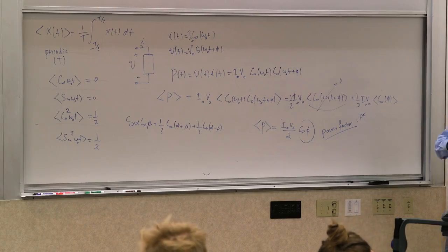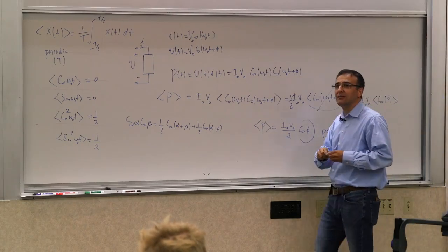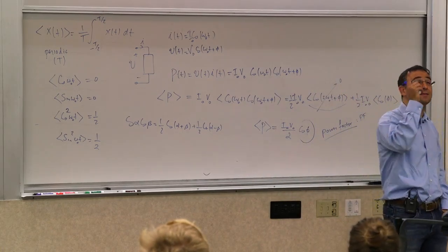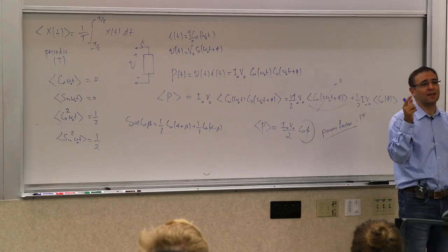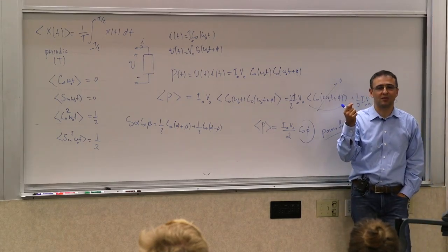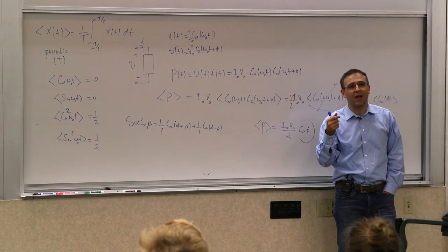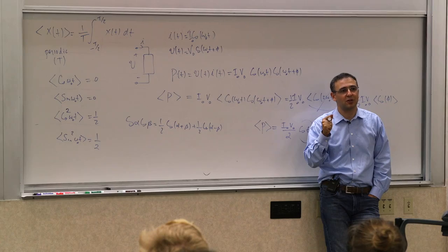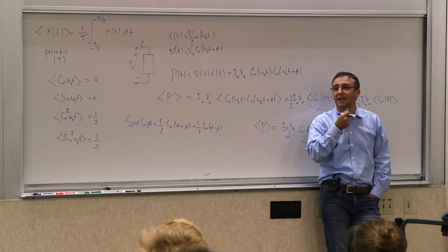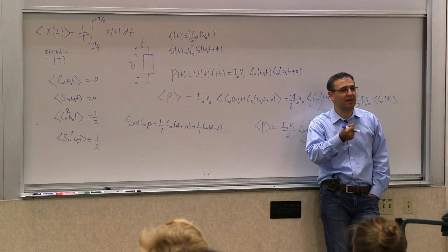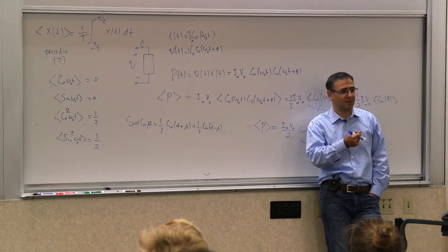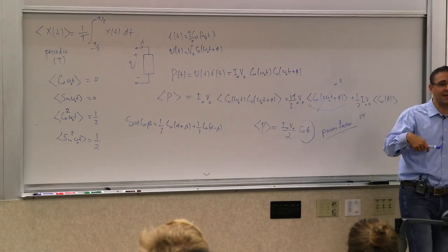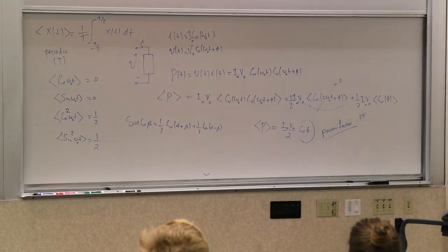And that's important. Actually, when you do power delivery in the power transmission network and power generation, these fluorescent lights actually look inductive because of the way they operate. So if you have a large number of these fluorescent lights, sometimes your power factor starts going one direction. The same thing is true about big electric motors. Big electric motors appear inductive to the network. So they start creating a leading power. They call it leading if it's positive, and lagging if it's negative. They create a lead in the network.